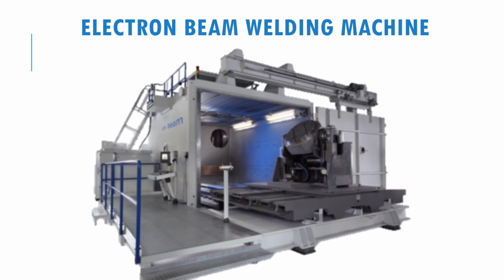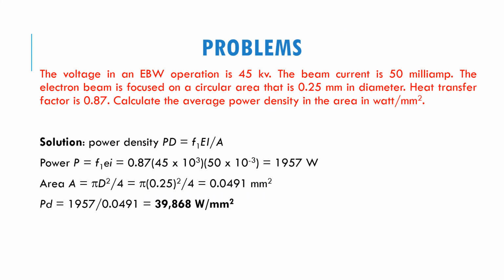So here is an example of a machine for electron beam welding. Okay, so let us look into the problem for the EBW. The voltage in EBW is 45 kV, current is 50 milliamp, focused on a circular area 0.25 mm in diameter, heat transfer factor F1 equal to 0.87, and calculate the average power density in the area in watt per mm squared. So now let's see the solution.